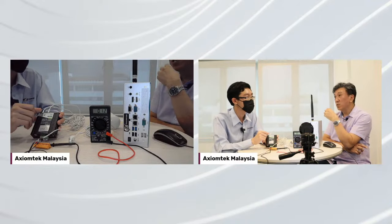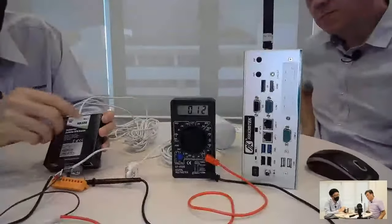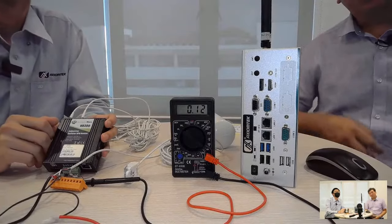That is quite a high power consumption, especially for remote sites that usually run on solar or on battery mode. The sleep mode will help you cut down half of the power. As you can see over here, the device is now in sleep mode, so the current consumption is around 100 milliamps. This is the sleep mode case.